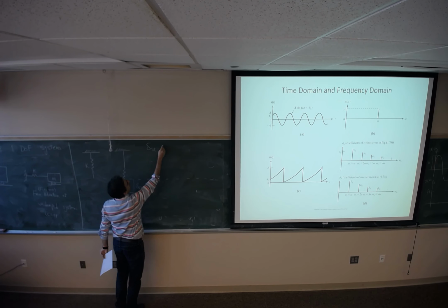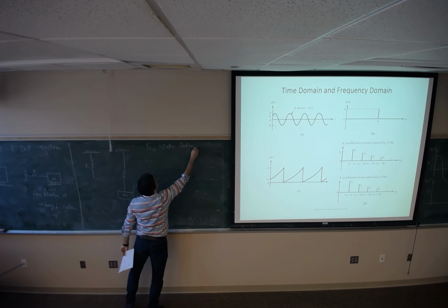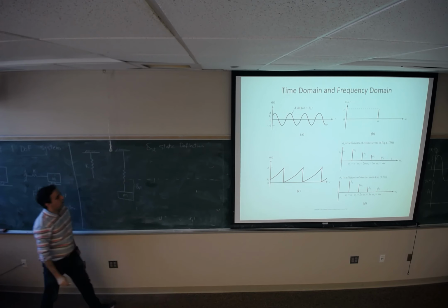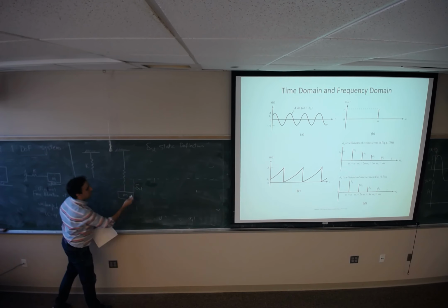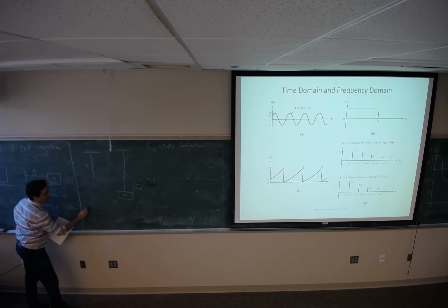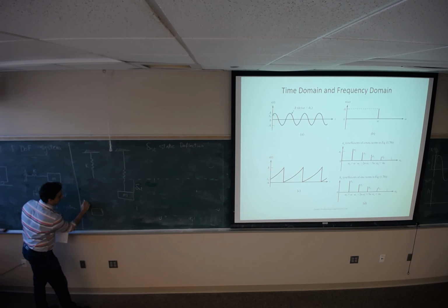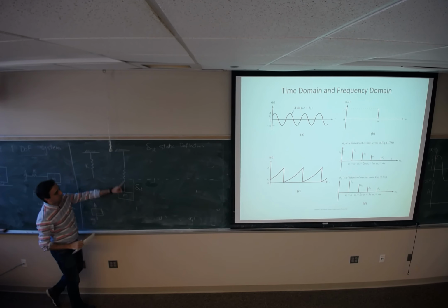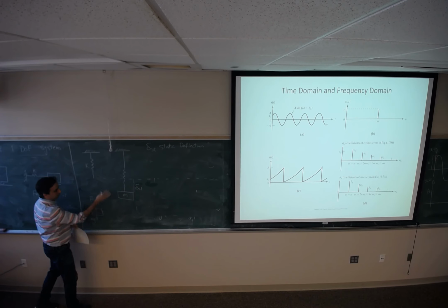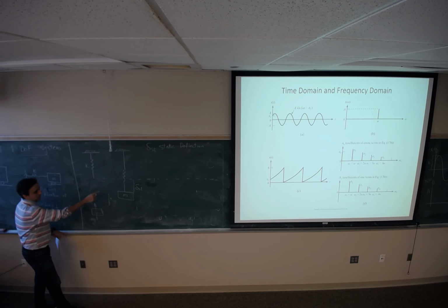Delta static is the static deflection. Why do we have static deflection? Because of the weight of the mass. How much would be the static deflection? If I draw the free body diagram of this, mg is going down, and the force coming from the spring should apply from the opposite direction. Summation of the force must be equal to 0. So I consider this direction as positive.